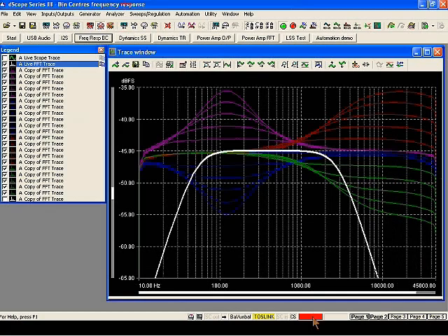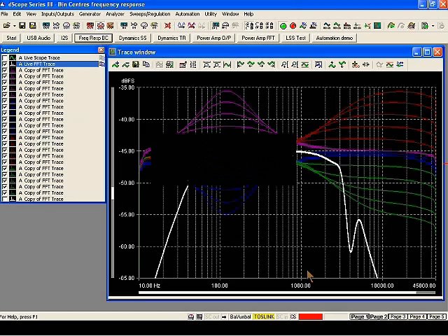What I might also do as a potential loudspeaker designer is to dial in a notch filter to deal with a cone resonance issue around about 4 kHz. So there you can see I'm just dialing in a slightly different flavour of EQ as well. So this is a great way of making frequency response measurements, particularly electrically. This is an electrical measurement I should have added at the start there. And it gives us a really powerful and flexible way of measuring many different curves in a very short space of time.